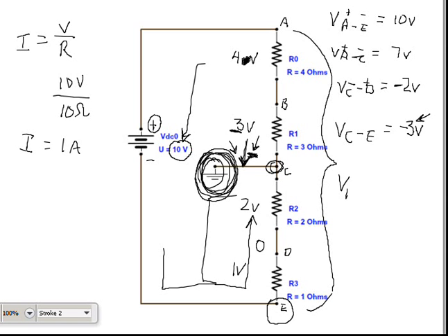If I'm measuring point D to E, well, I'm no longer forced by that symbol. Point D to E, I can go back to that, and it will be. It's only when your measurement point includes the ground symbol do you have to put your negative probe on that point. I hope I'm making that clear.